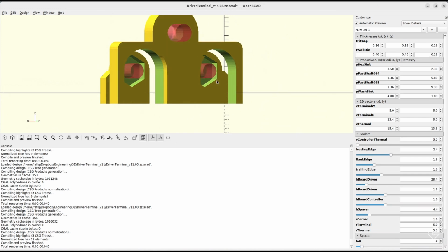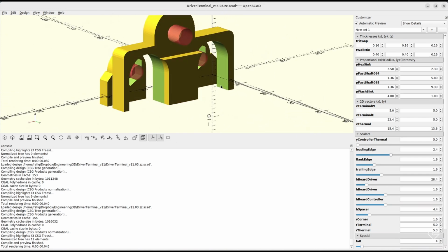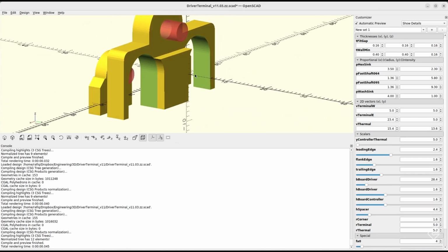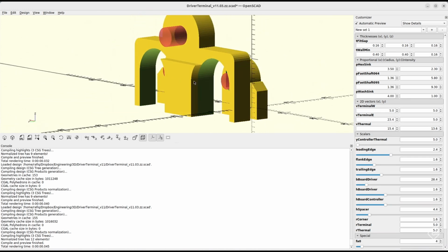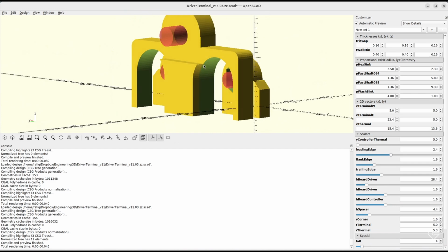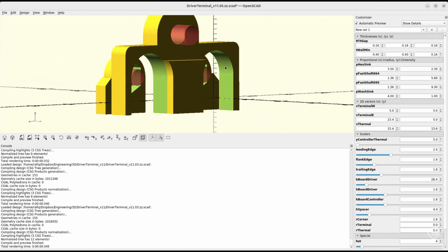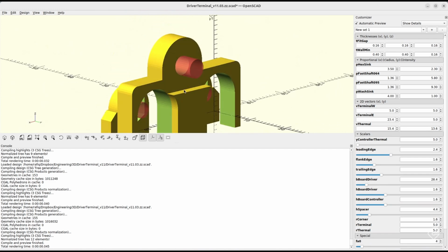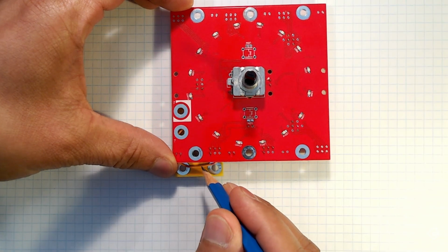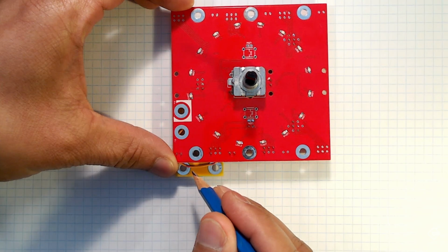So when we render it, there's the new solid we just created. And hopefully now you can see where all the components of the polygon are. You can see here how this arc starts at the 0 angle and then proceeds up to that calculated angle. And then on the other side, it starts from that calculated angle and it goes to 180. And that flat portion right there is 5 millimeters away from the center of the thermal terminal to fit snugly right around here. Now we're moving on to the last portion of our solid.